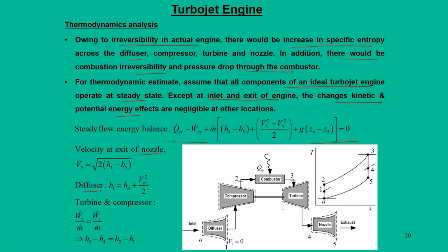Ideally, when you say jet engines, normally these particular relations hold good. The turbine drives the compressors, so the work generated by the turbine is equal to the work consumed by the compressors. So, with these working equations, we can solve this jet cycle, the turbojet cycle.